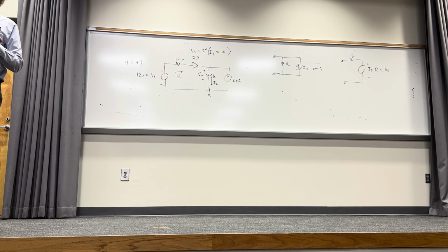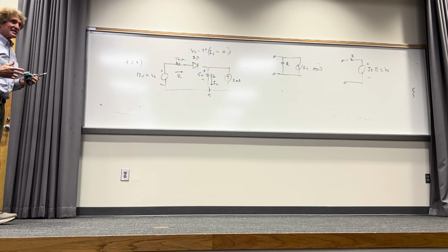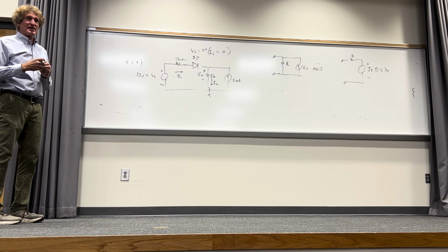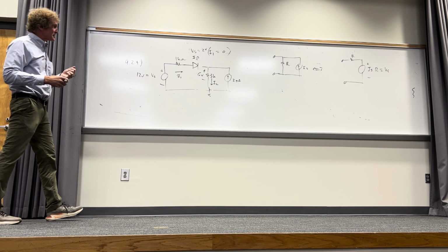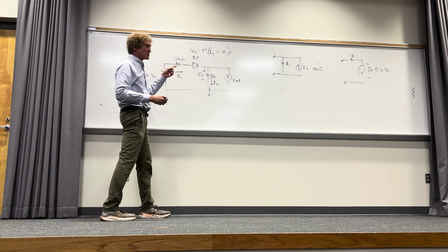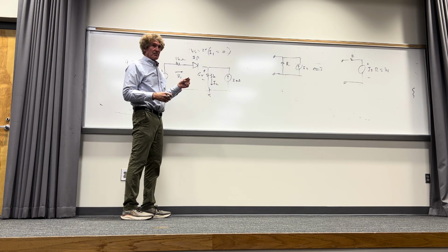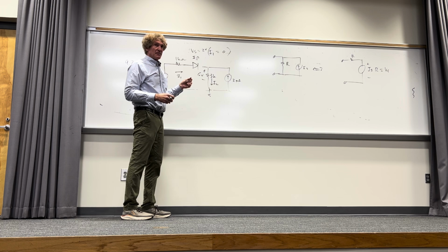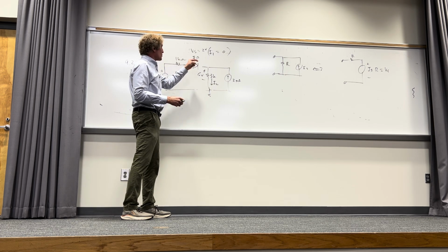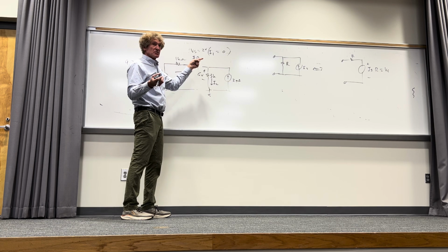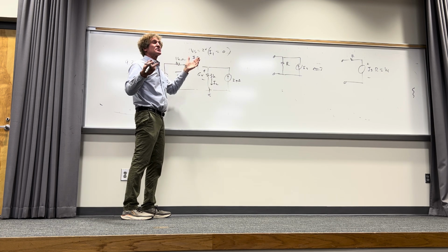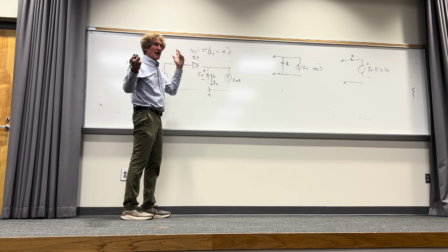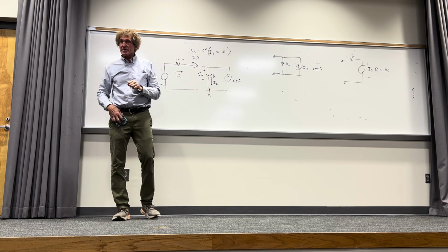All right, if you see that, you basically got a handle on this stuff. You're starting to inspect things and you're getting an idea of how you go about business. Basically, if that diode's on, it's a short circuit. What does that mean? Well, if it's on, I could replace it with a short, do the analysis, and if current's going in the direction it's allowed, it's a short. If it's going in the direction it's disallowed, it's an open. Just cut the wire out, you might say. Follow me? That's it.